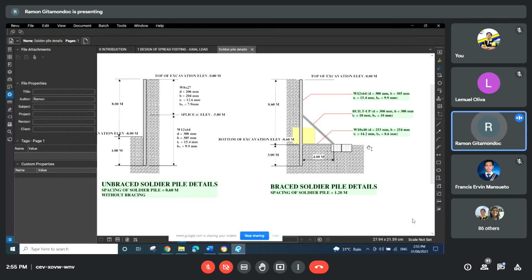When it is dry, the soil is very hard, but when it gets wet it becomes very soft, no? If you step on it, you will even sink, no? So, of course, with low bearing capacity for the anchor block, the anchor block sinks, no? That causes tilting forward of the sheet piles, no?